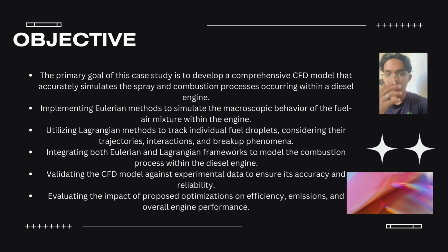Okay, we have six primary objectives. That is to implement the Eulerian method to simulate the macroscopic behavior of the fuel-air mixture within the engine. We also want to utilize the Lagrangian method to track individual fuel droplets, considering their trajectories, interactions, and evaporation. We also want to integrate both Eulerian and Lagrangian frameworks to model the combustion process within the diesel engine. Then we want to validate the model against experimental data to ensure its accuracy and reliability. Lastly, we want to evaluate the impact of the proposed optimization on efficiency, emission, and overall engine performance.